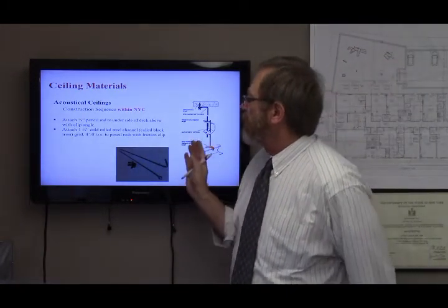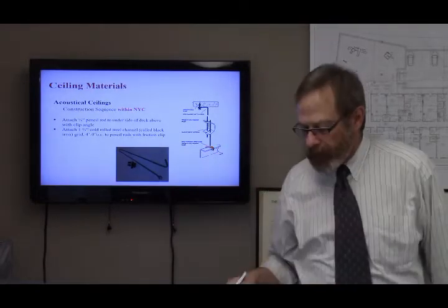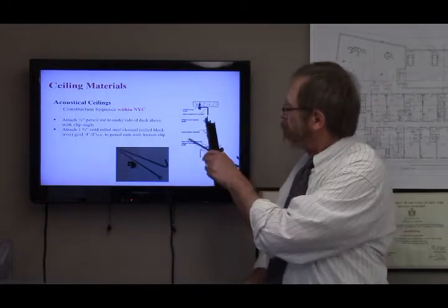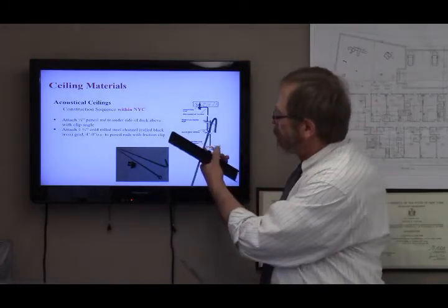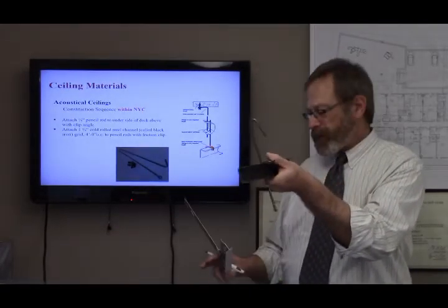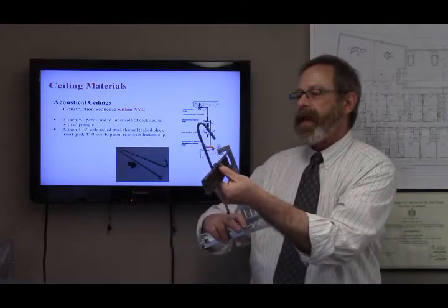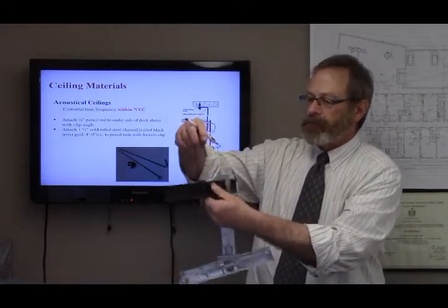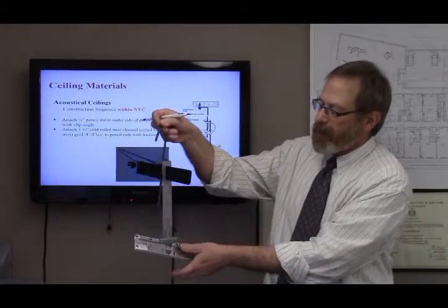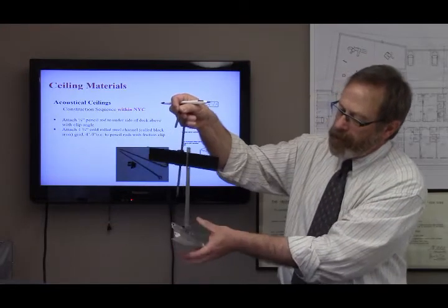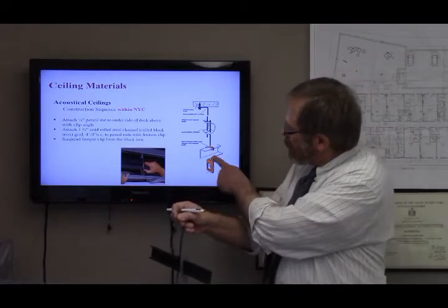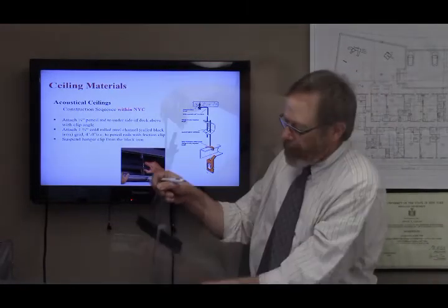So we're going to attach to that friction clip the 1.5 inch channel, black iron we call it, as we discussed earlier. And then we're going to put a hanger onto that channel. And that's specially made to accept a rod hanger over it.